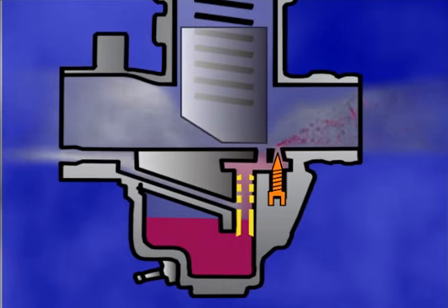It should be noted that some carburetors have a pilot mixture screw on the air intake side of the carburetor. In this position, the screw controls the amount of air entering the pilot circuit, thereby affecting the circuit's discharge. This reverses the adjustment procedure when adjusting the pilot mixture screw.